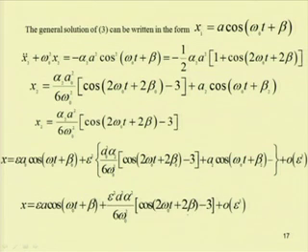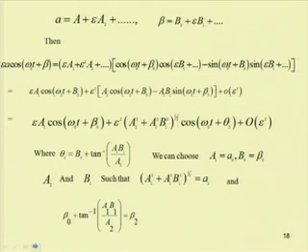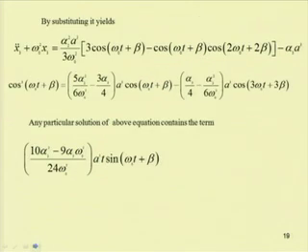We also observed that in the straightforward expansion method, the response amplitude or the frequency of the response is not a function of the amplitude of the response. In a nonlinear system, generally we observe that the response frequency is a function of the amplitude, but as this method is not showing this behavior, it has to be modified. In the last class we saw that by modifying this method we used the Lindstedt-Poincare technique.